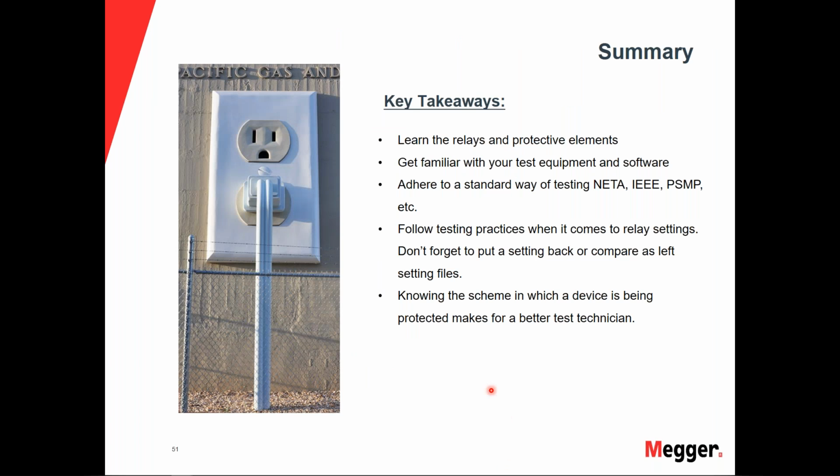Okay, so in the summary, there's just a few takeaways. What we want to do is make sure that we learn the relays and we learn the protective elements in those relays, which makes us better to test. We need to know what's happening so we can test it. We need to get familiar with the test equipment and the software. We definitely don't want to run out there on day one unzipping everything out of the plastic and ripping it out of the bags and installing drivers and installing software, and we're sitting in front of a relay panel on day one, getting ready to learn on location. We need to be familiar with our test equipment before we even go out in the field.